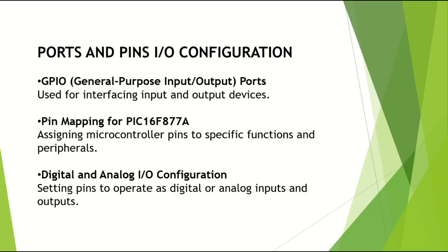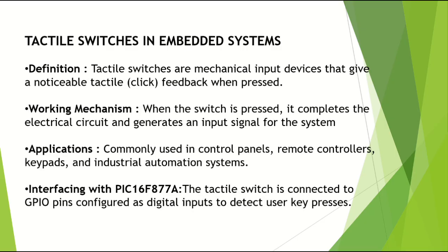Tactile switches in embedded systems. Tactile switches are mechanical input devices that give noticeable tactile feedback when pressed. Working principle: when the switch is pressed, it completes the electrical circuit and generates the input signal for the system. They are commonly used in control panels, remote controllers, keypads, and industrial automation systems. Interfacing with PIC16F877A: the tactile switch is connected to GPIO pins configured as digital inputs to detect user key presses.